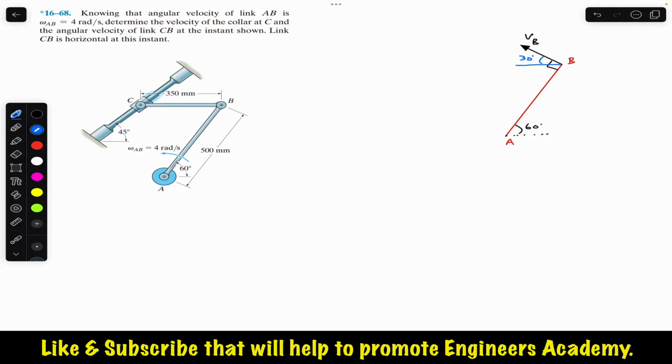And we can find the velocity of B by applying V equals R omega. So this will be equal to the length of this link AB, which is 500, times the omega of link AB. Omega is given for link AB, which is 4 radian per second. So this will be basically 500 into 4. So this is 2000 mm per second, the velocity of point B.